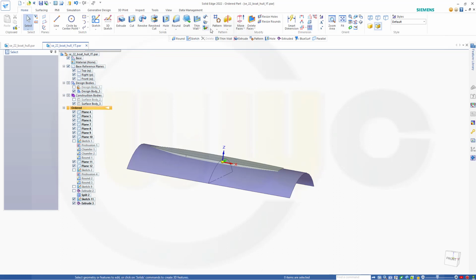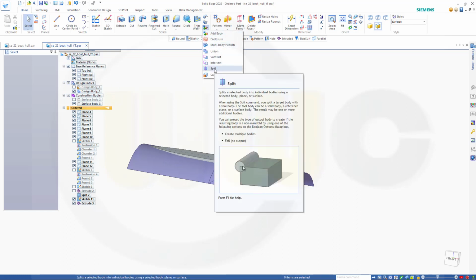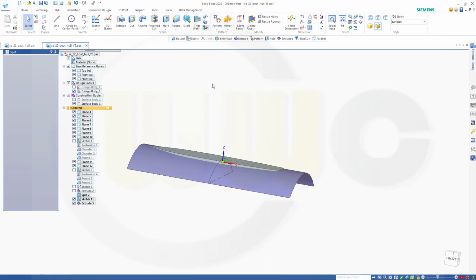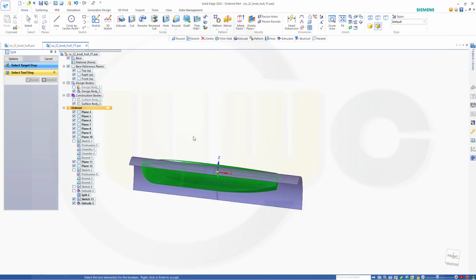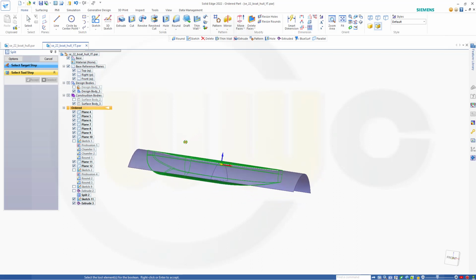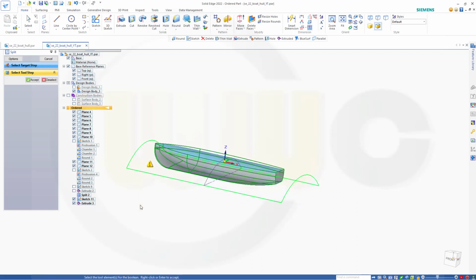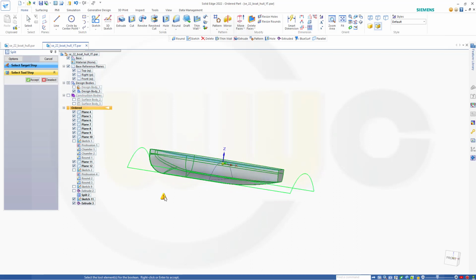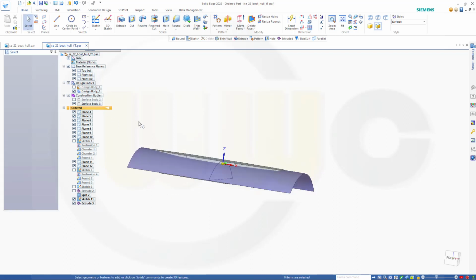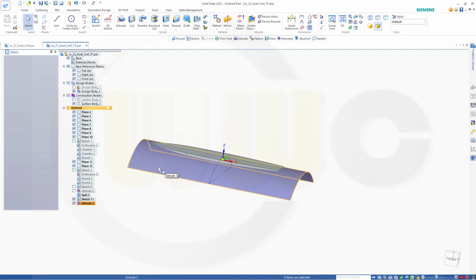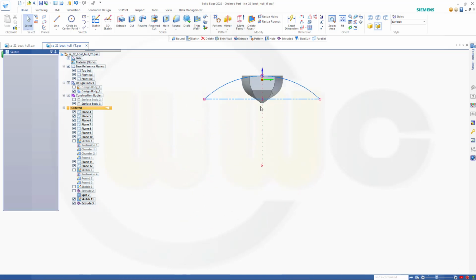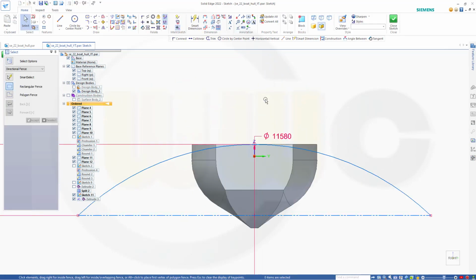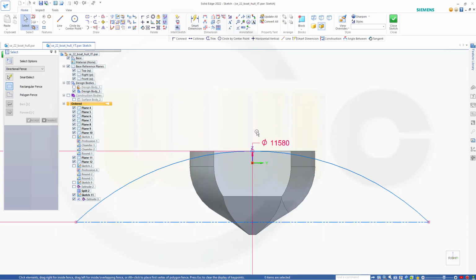Let's try once more. And I might run into that parasolid problem. Split, I want to split this body here with that tool. See, there's already a message, Boolean operation on solid failed. That's because there's that tangency here. So in order to fix that, I need a distance. So that sketch here should be not tangent here, but there should be a distance.